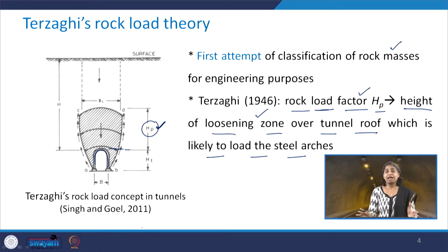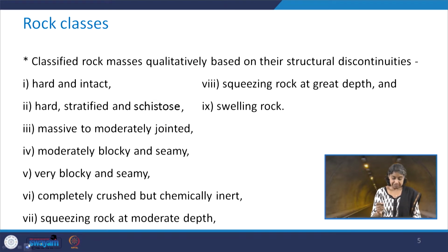Now, what should be the value of this rock load factor? This will depend upon the type of the rock mass through which the excavation is made. First, Terzaghi defined those rock types or rock mass types, and then accordingly he prescribed the different values of HP corresponding to each of those rock load classes.